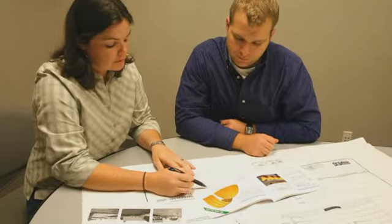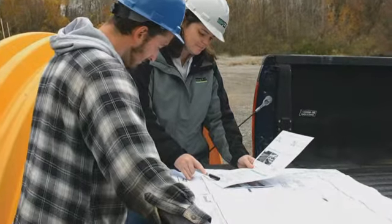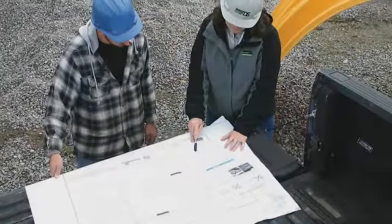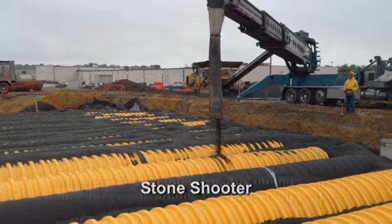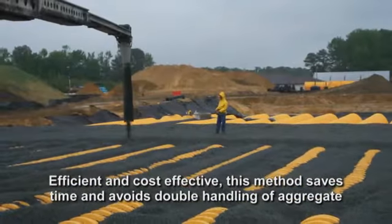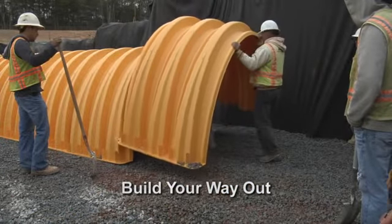The first step is to set up a pre-con meeting to discuss the required steps, establish a timeline, and determine an appropriate method for placement of embedment stone. Here are three commonly applied methods. With method 1, a stone shooter located outside of the excavation evenly places embedment stone over the entire bed in a continuous manner. Method 2, the most commonly used method, is to lay one or more chambers at a time across the bed.